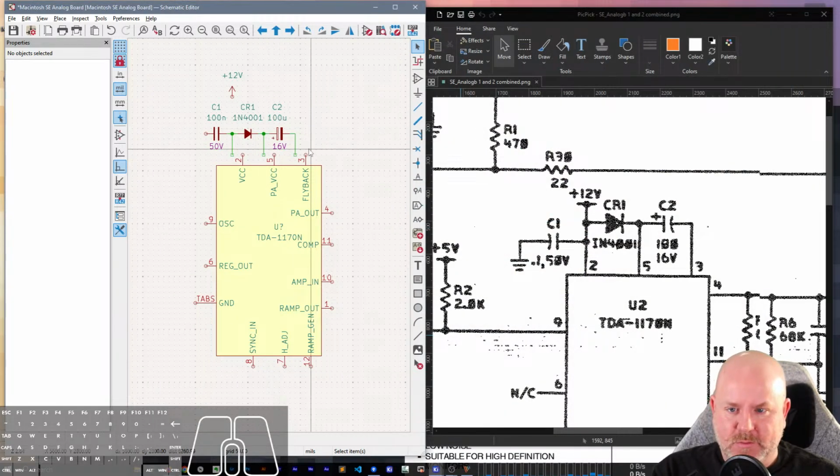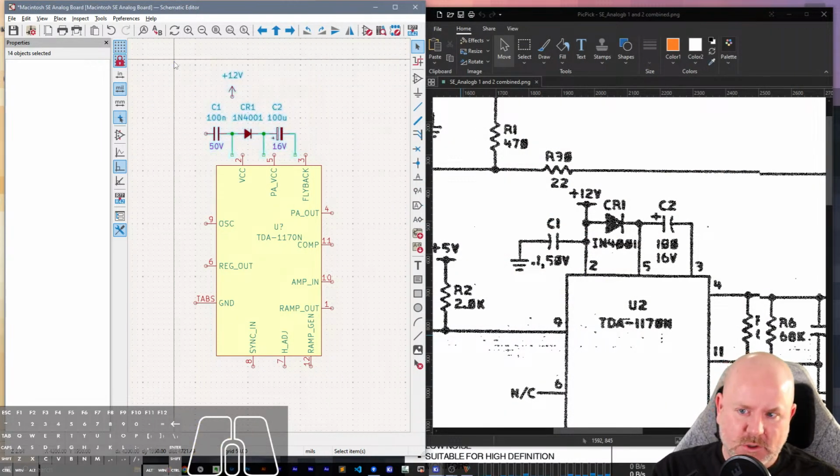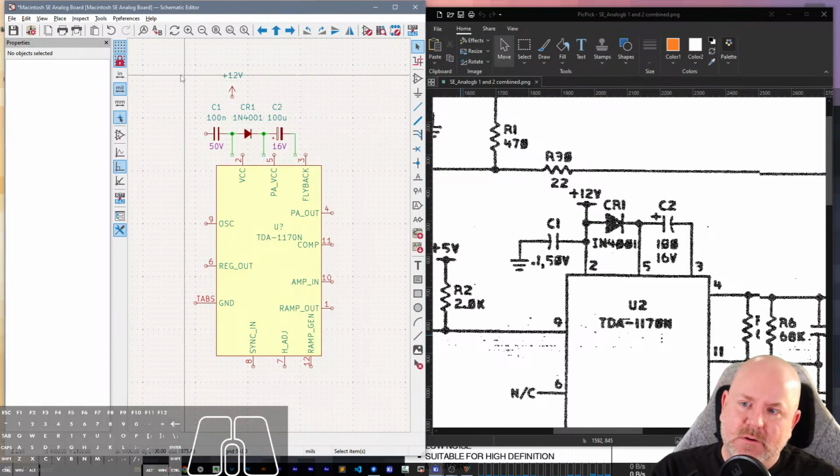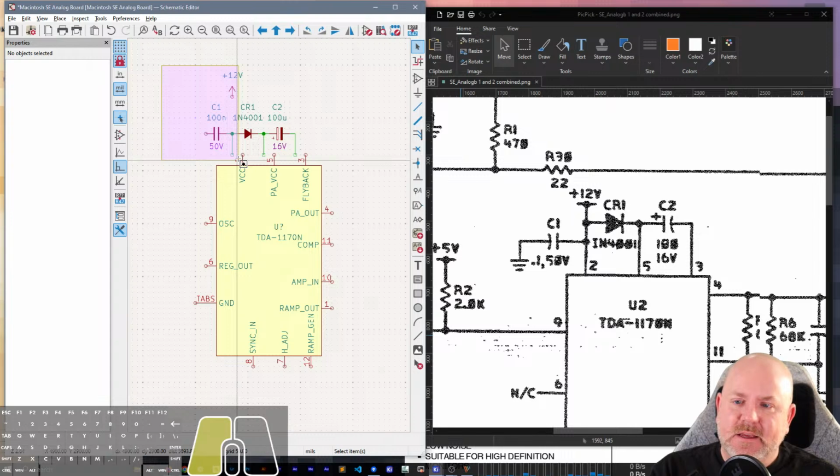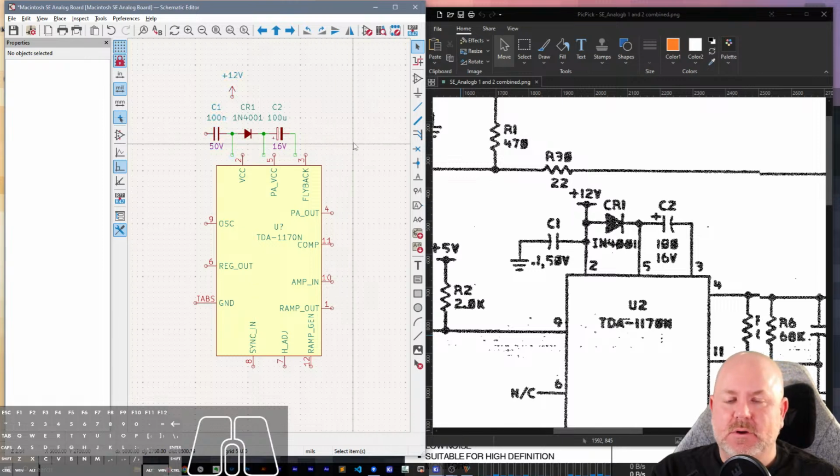I'm going to minimize because we're probably going to move stuff around in a second. So left dragging. Remember, there's two ways to drag and select. Dragging to the right, anything that fits entirely inside of the bounding box gets selected. But if you drag to the left, anything that touches the bounding box gets selected. So like here, all three of those components, all the wires, and the 3 value labels are going to get selected. Although I guess those got selected because we selected the part, right?